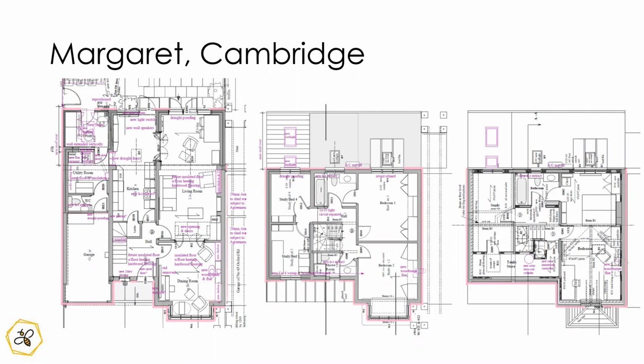It'll be bigger than an 8 kilowatt unit, which is only one fan. But when you go up to the 11 kilowatt, for Mitsubishi anyway, that is 2 fans anyway. So there's not much difference in size between that and the 10 kilowatt one. But the 8 kilowatt one, if you can manage with it, might be a better option. That's what I was wondering, if we could really go down to 8 and push it.